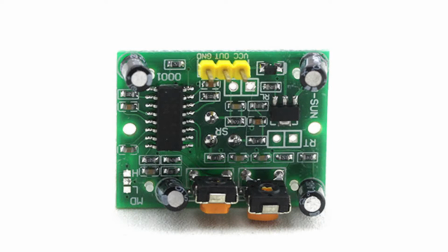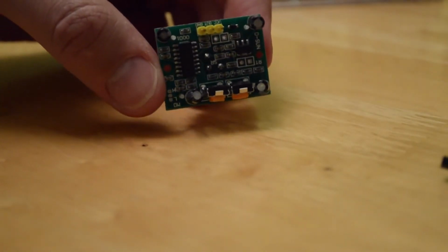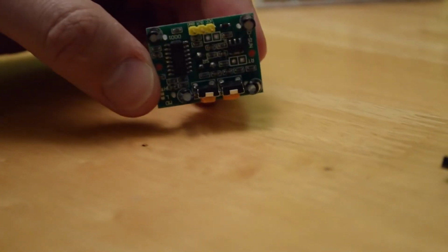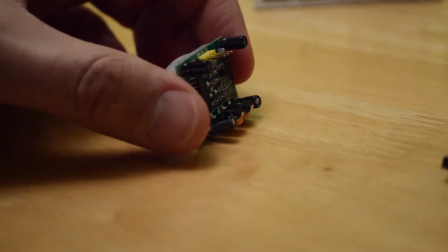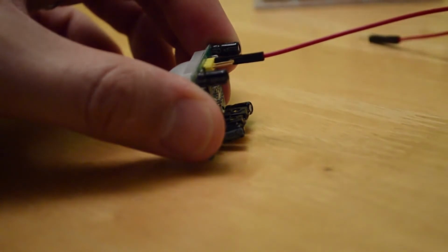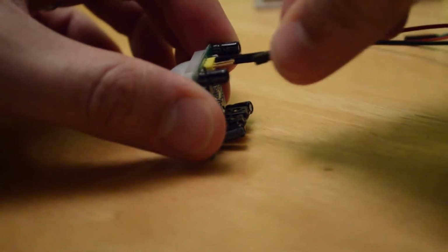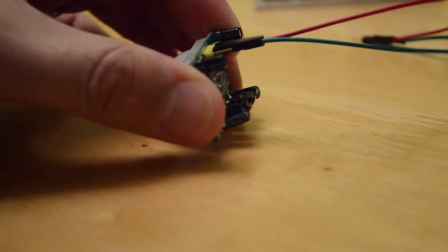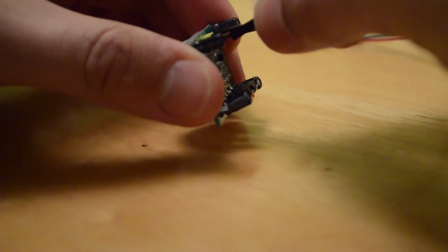So this is the actual module that you have. You notice at the top there's the yellow pins, and you've got the VCC, which is the positive voltage, the red wire. You've got the GND, which is for ground, which is the black wire, and the out, which goes to your GPIO on your Raspberry Pi. So let's have a look and see how we wire this up. So here we have our PIR sensor, passive infrared sensor. I found it easiest to wire this up first before doing the rest of the breadboard. So let's just connect this up. We put the red to the 5-volt rail, the new 5-volt rail we just connected, or we will connect in a minute. Obviously whatever colour we want to the GPIO, and then the black to the grounds.